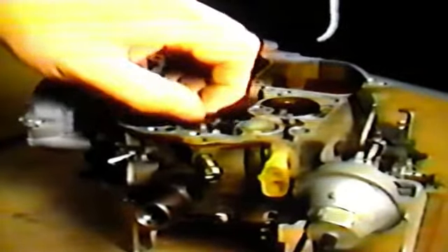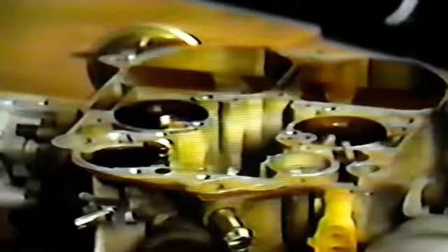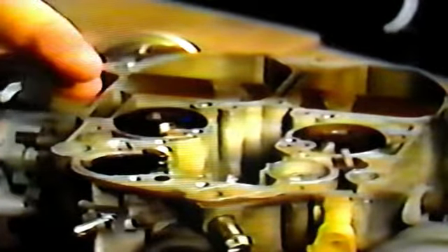The next thing that needs to be done is checking the carburetor float weight. This has become necessary because of the increase in alcohol mixed fuels around the country. Factory specs for this particular carb float call for a weight of 7.5 to 8 grams, but you could probably work in a range of 7 to 8 and still be okay. This float weighs in at exactly 7.5, indicating that it's in good shape and can be put back in place. When repositioning the float, make sure to check the float level and then set it to factory specs. This is the basis of correct fuel management in any vehicle.